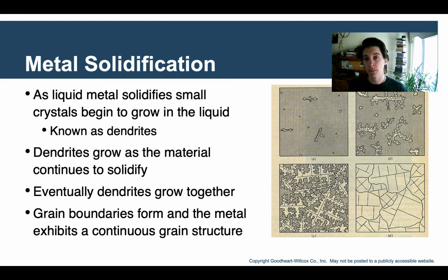As this liquid metal solidifies, the crystal structures we talked about join together and form bigger crystal structures called dendrites, the little pieces right here that are starting to join together. This is a big liquid soup of metal, and these little pieces join together as it solidifies and cools, and they get bigger and bigger until it's at its cooled state. Then you have these larger grains.